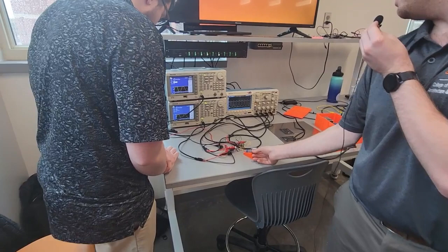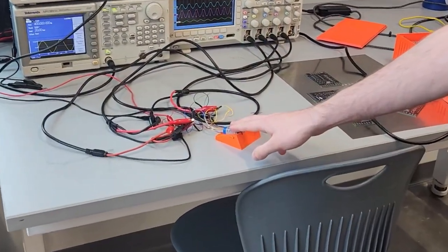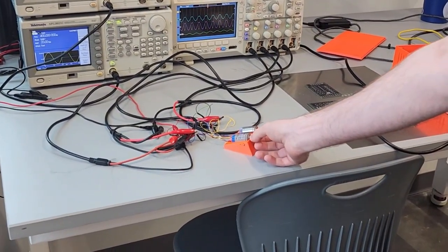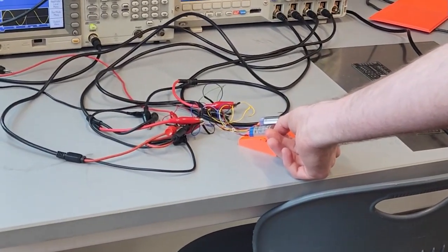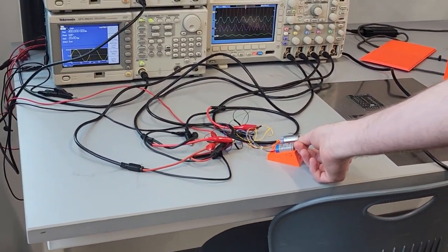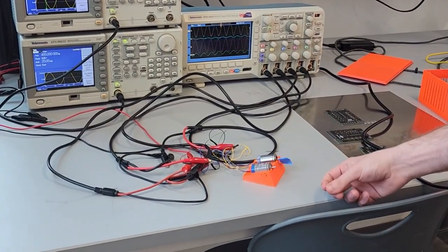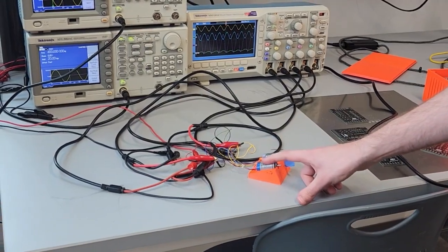SimStar gave us the task to turn the transmitter synchro to digital. So both of these are synchros, and as you can tell, as you turn it, there's a three phase signal happening on the oscilloscope. Basically, what a synchro does is this will always go back to its position wherever the transmitter's at.